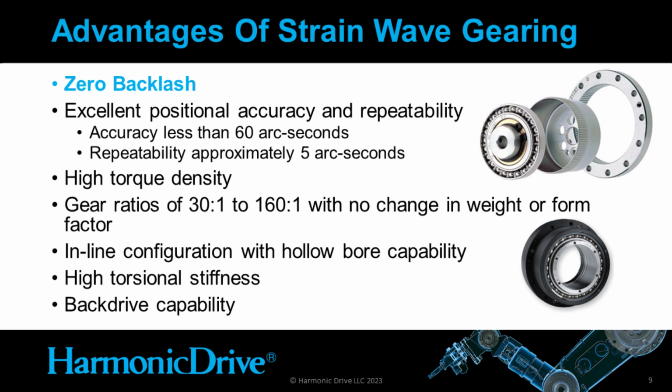You can see in the bottom right side a very large hollow bore. Harmonic drive strain wave gears also have high torsional stiffness, and the high gear ratio units also have a back drive capability, which is uncommon for very high gear ratio gearboxes.